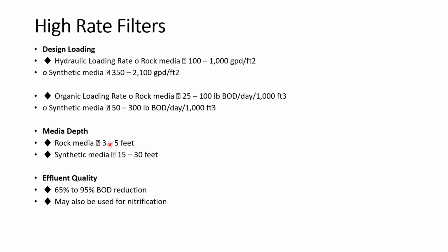So the rock media here is usually 3 to 5 feet tall in the tank, and the synthetic media is around 15 to 30 feet is packed in the tank. From the high rate filters, around 65 to 95% of BOD reduction is obtained, and here it can also be used for nitrification process.